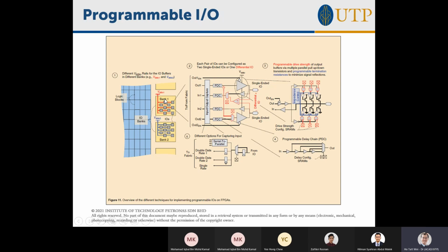So the programmable I/O is able to handle this. Let's say the logic is implemented in individual logic blocks, then they are routed out all the way to the specific I/O pin, and you can choose which I/O pin they route out to by the pin assignment. But for that pin itself, you have a choice. You can choose whether it is 3.3 volts, 5 volts, or 1.8 volts. So it's just choosing which driver it is, or differential I/O. Differential I/O requires the FPGA to actually use 2 pins rather than 1 pin. That's why it's called programmable I/O, because you can specify it, and it works the same way: it's just setting a few SRAM bits, which will enable some multiplexers to connect certain wires.